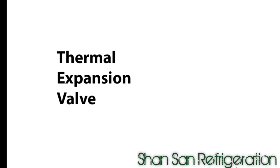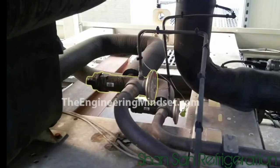The next expansion valve we're going to look at is the thermal expansion valve. In the real world, the thermal expansion valve looks something just like this. So this one is actually on an air-cooled chiller, but it's still got the flow of refrigerant coming through and then going off into the evaporator, and you've also got the equalizer valve coming through there, and attached to the top of the thermal valve is the capillary tube which goes off and measures the superheat.